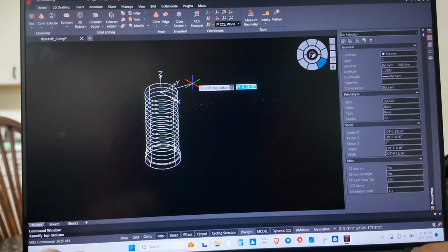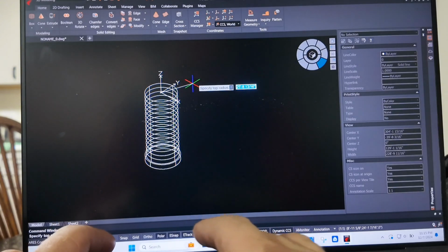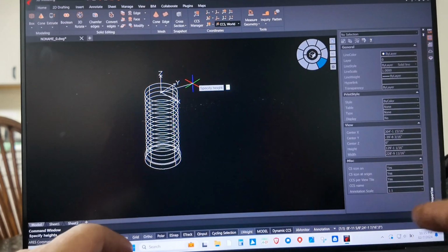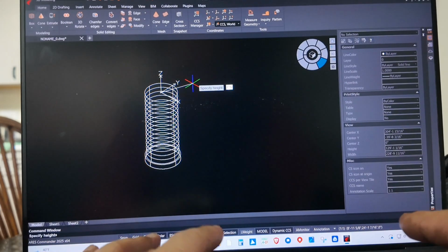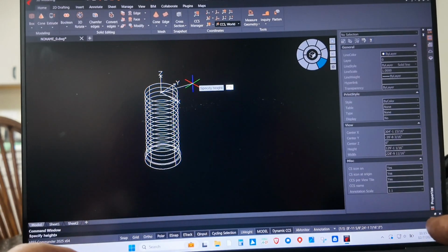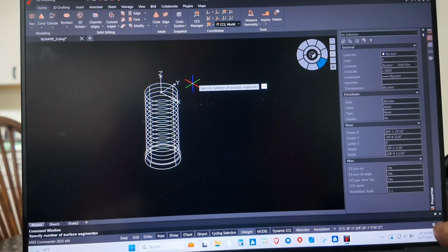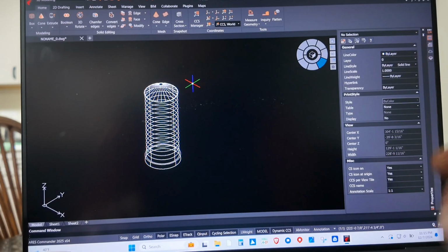12.5 foot radius for the bottom. Top radius is 16 inches. And the height is going to be 7.5 foot, because it's going to be half of what the 48-foot bin was. Number of surface segments, 24 roof panels on a 24-foot bin. There. We have our wet bin.